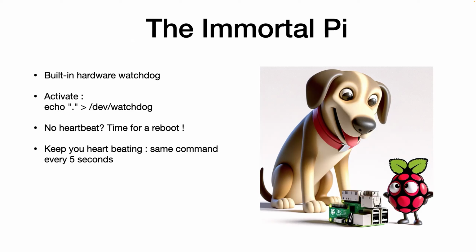So you keep the hardware watchdog in the know that the OS is running correctly. So we have selected a 5-second interval. It gives us a little bit of leeway in case the system is slower. So make sure that the hardware watchdog does receive the heartbeat.